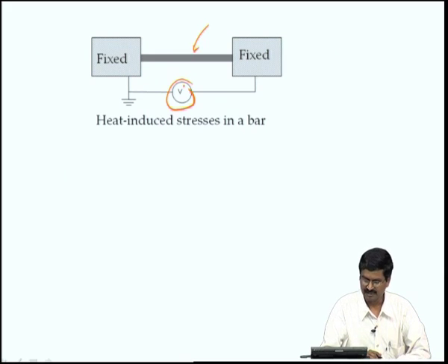Now, when there is a voltage, there will be certain current going through this, and because of the current there will be Joule heating of this interconnect or a beam, if you will. So, it is suspended between 2 points where it is fixed at both ends, and there is a current going through and there is a heat generated because of the current passed through it. It is a very common situation in microelectronic circuitry as well as microelectromechanical systems components.